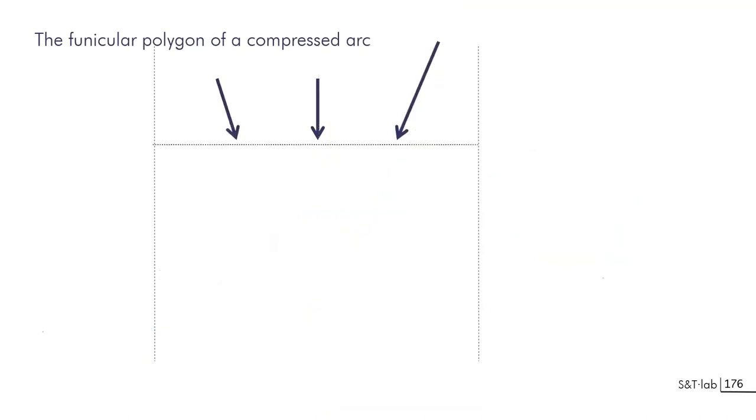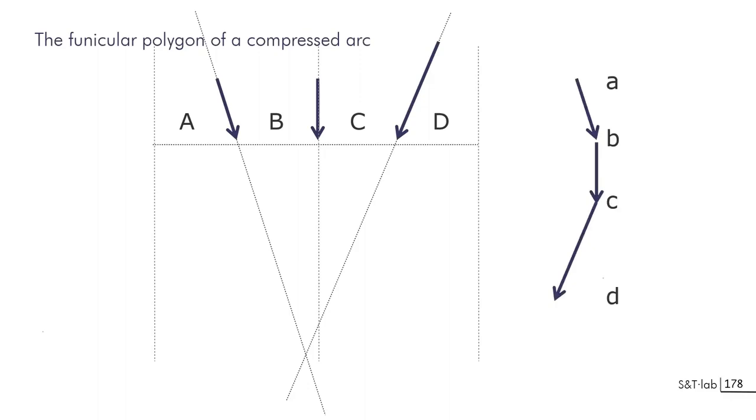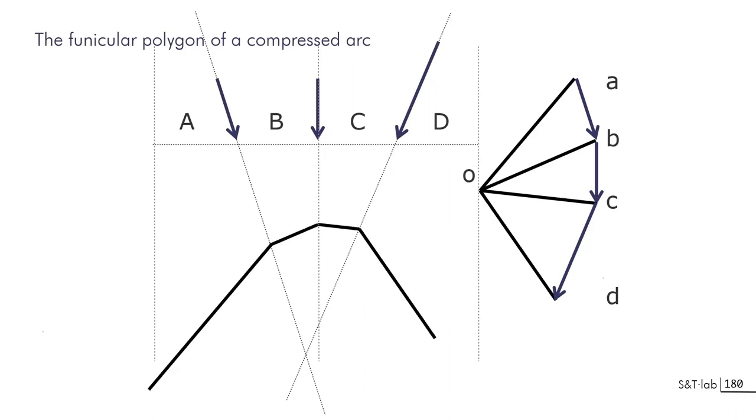And what about non-vertical forces? As you can see here, these forces are not fully equilibrated, and so you have movement on one side of the system, and this construction of the funicular polygon will help you to define this. So let's construct the load line that is not rectilinear. This is curved. In this case, let's get a pole and get the rays. Let's get the funicular polygon, and let's get the resultant.